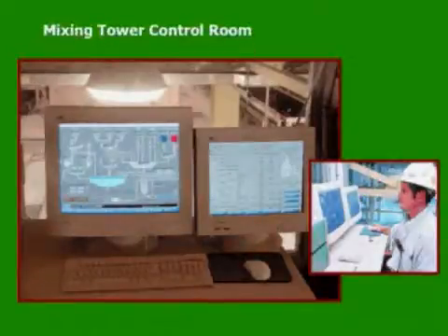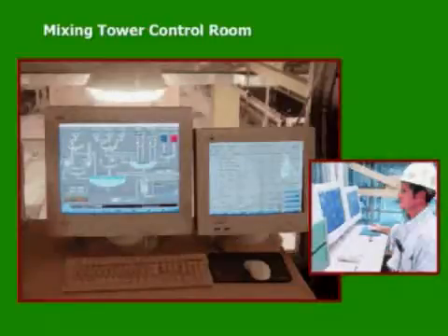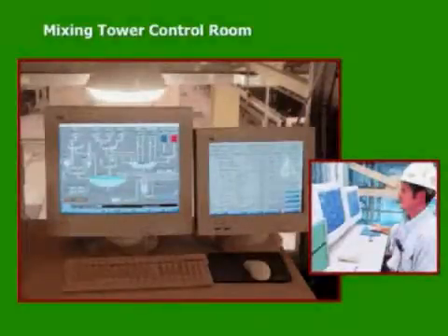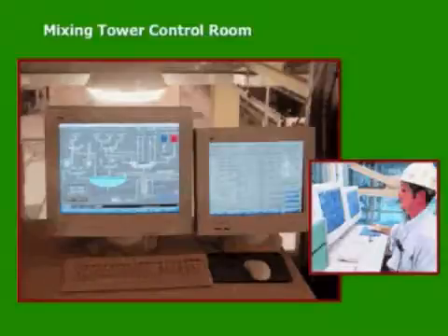Most AAC facilities are well advanced and have just a few workers. Everything is computerized, with robots pouring, moving, and autoclaving the product. The technology today makes it possible that each mixture ratio is very accurate, controlled by computers, and the material has just 1/32 of an inch size differential.